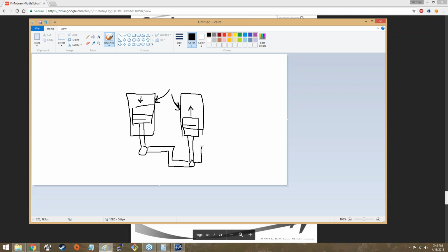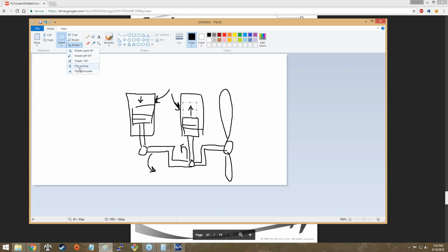And this is actually further connected. Let's say it's connected to the propellers. And what it's doing is it's making this shaft spin, and it's spinning up this way, which is forcing this piston upwards, which is repeating the process over here. The air in here gets compressed until it's hot enough to ignite the fuel in the air-fuel mixture, forces this piston down. Forces that piston down and forces this piston up.